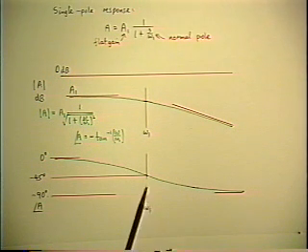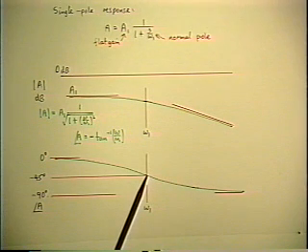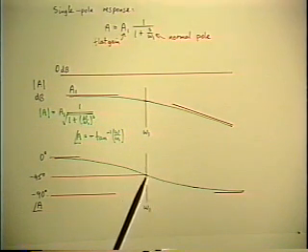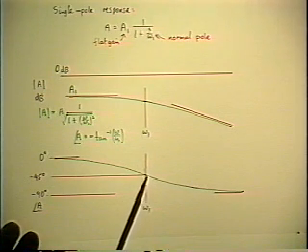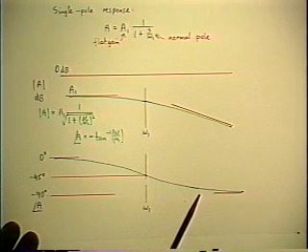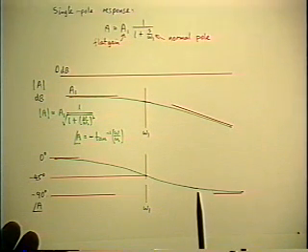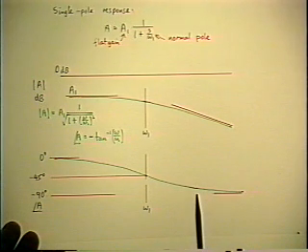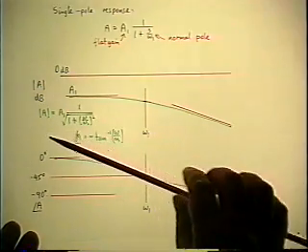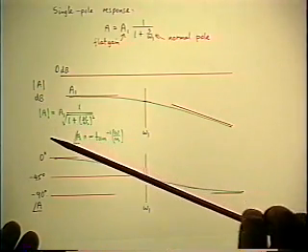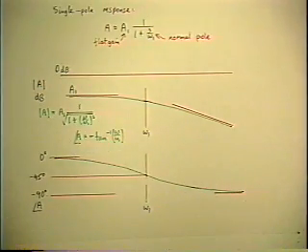The first idea might be, let's find the slope of the arctangent function at the symmetry point, which is the corner frequency, and let's extrapolate that straight line until it intersects the other asymptote, and let's find what the value of that frequency is. Then we can mark it off on the picture, and when we want to make a sketch like this, we mark off that frequency, and then we can draw the straight line. Well, that's a possibility.